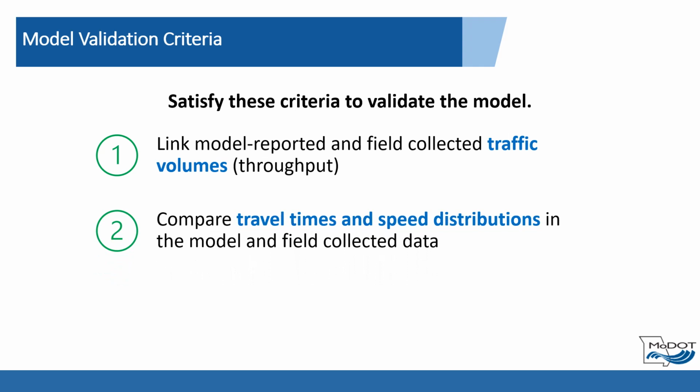Secondly, compare travel times between key points in the model and real-world data obtained from field travel time runs or big data sources. Adjustments to default or assumed speed distributions may be necessary to align model travel times to existing field conditions.